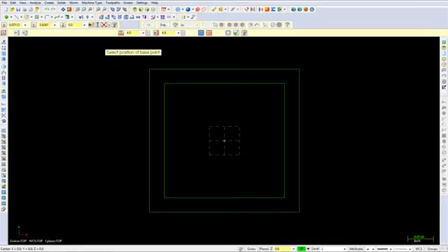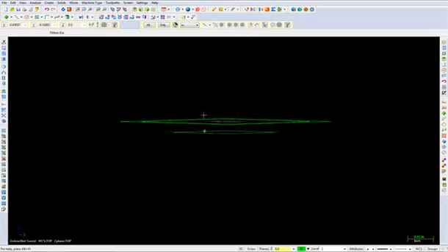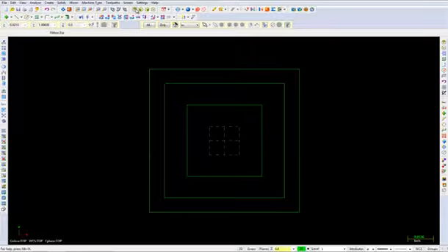Make sure that your construction mode is set to 3D down here. Then change your width and your height to 2.5 by 2.5. Change the x coordinate here to 0, the y coordinate to 0, and the z value to minus 0.375. Select the OK button and choose the isometric view to be able to see your wireframe geometry. Change the view back to top.